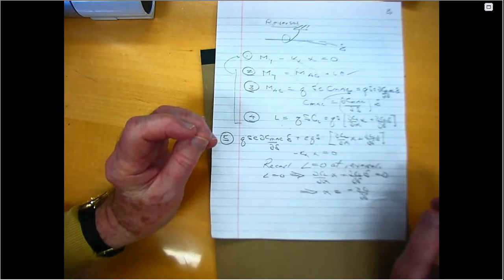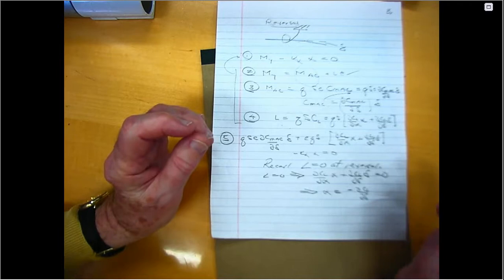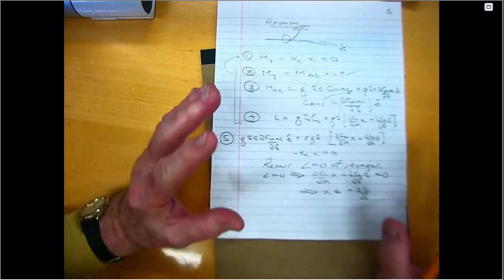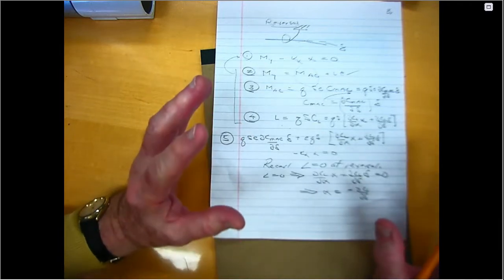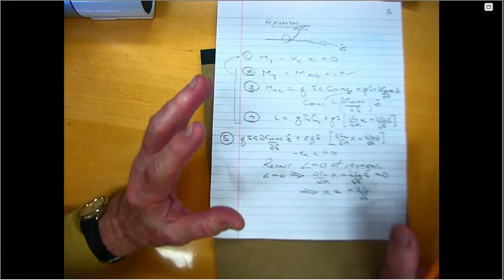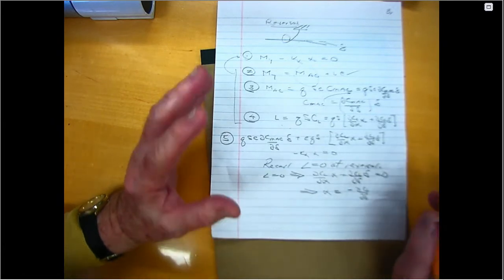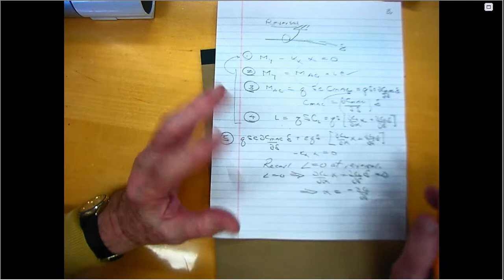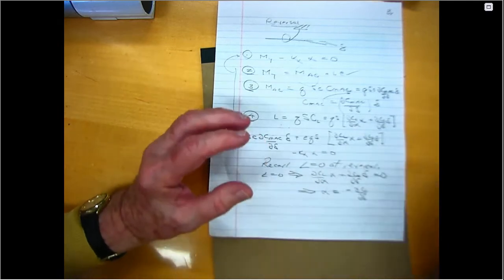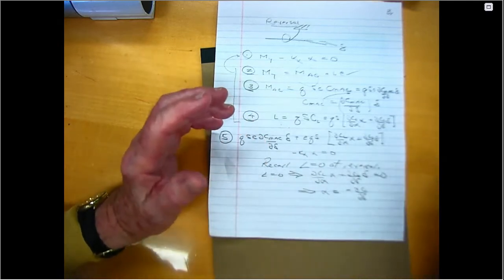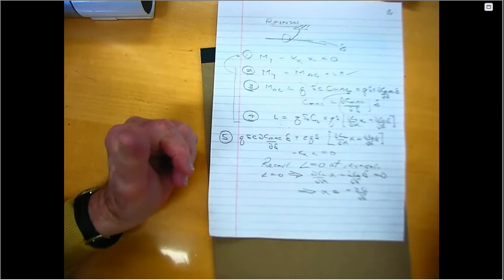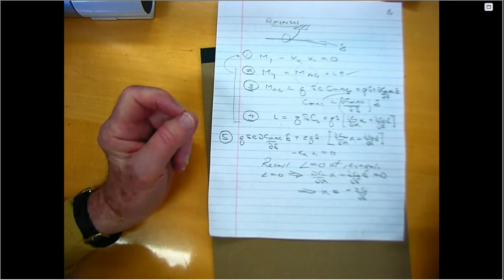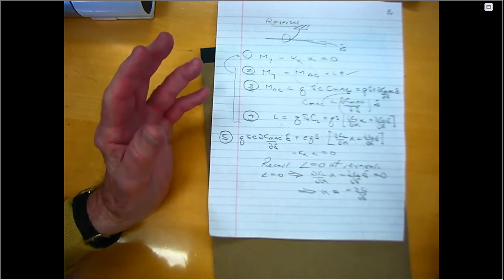Are we assuming lift zero? We are doing, for the purposes at hand, we are going to ask the question, is there a condition under which the lift can be 0? And to find that from our mathematical model, we're going to set the lift to 0 and then find out under what conditions that can be true. And it turns out there is a certain dynamic pressure at which the lift can be 0, just as there was a certain dynamic pressure at which divergence could occur. Does that help?